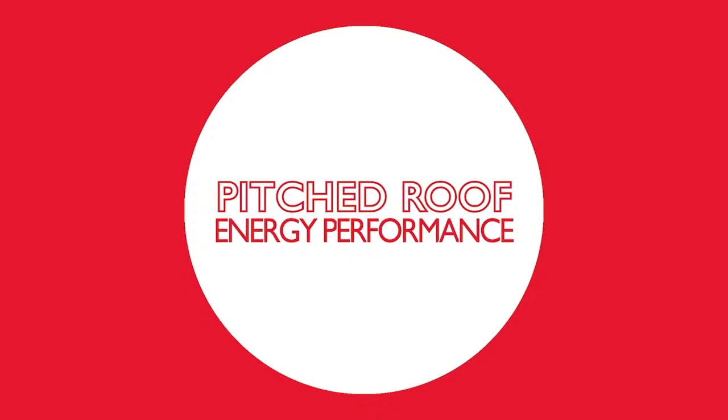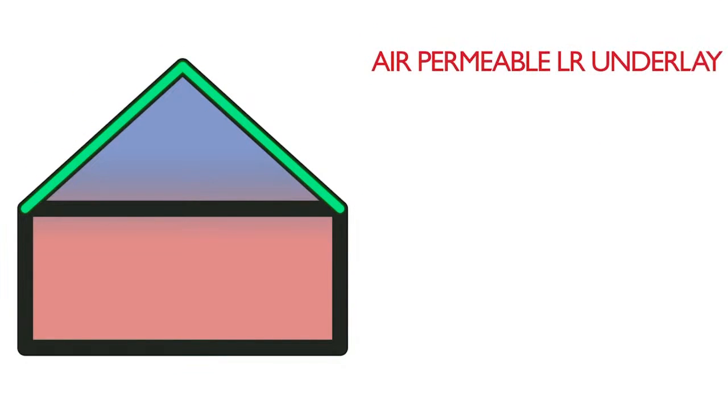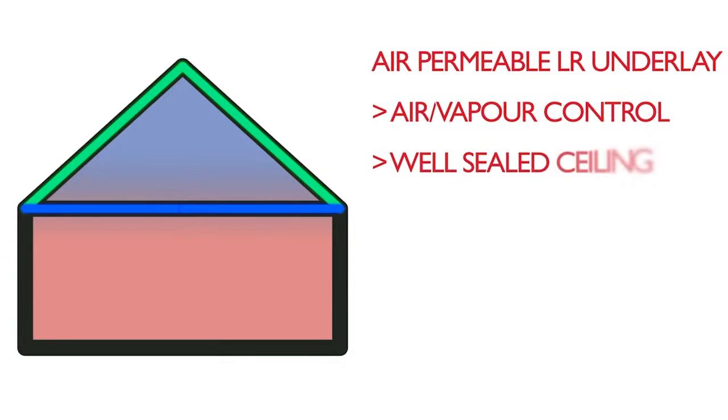When considering the correct roof type and underlay type, the effects on the overall energy strategy and anticipated air leakage rates should be considered very carefully. Whilst air-permeable LR underlays clearly present the most effective solution to ensuring moisture can escape from a roof structure, this does make the sealing of an internal air barrier, be it an air and vapour control barrier membrane or a well-sealed ceiling, of considerable importance.